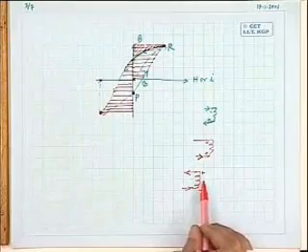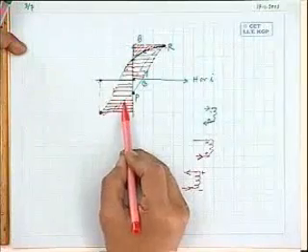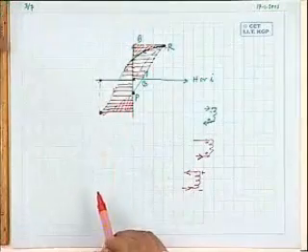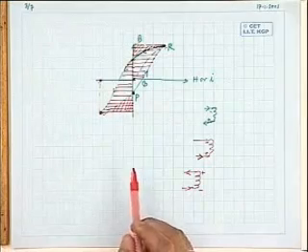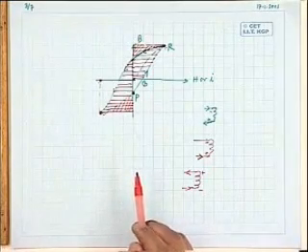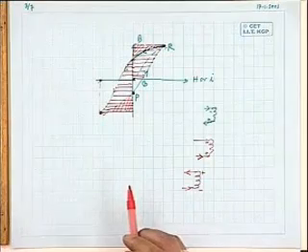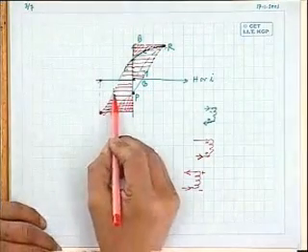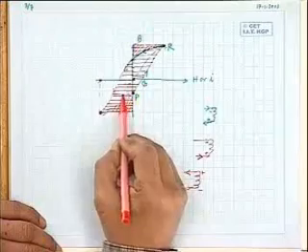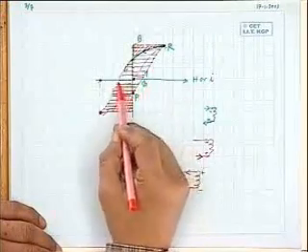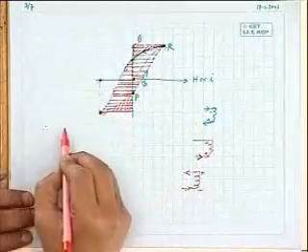So which area will represent that amount of energy delivered by the coil to the supply? It is this area. And this thing continues. So in each cycle, some amount of power is absorbed by this one and dissipated as heat inside the material. And what will be that amount of energy per cycle? It is this area. So this amount of energy will be the area inside the BH loop.